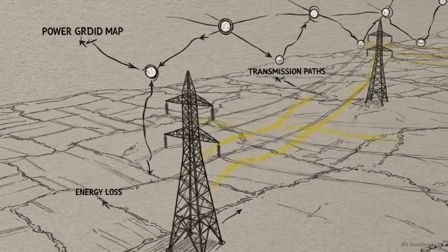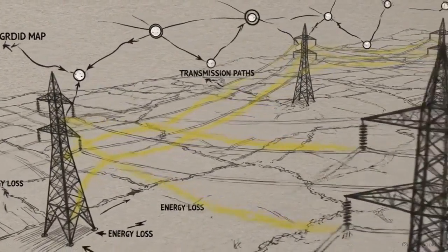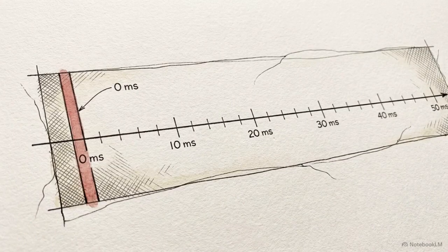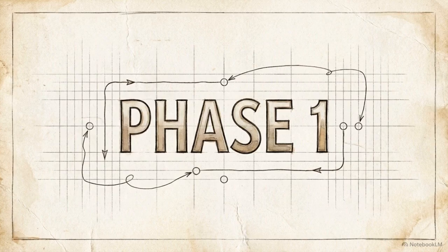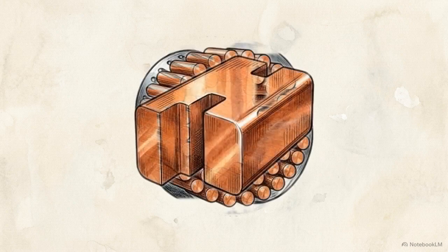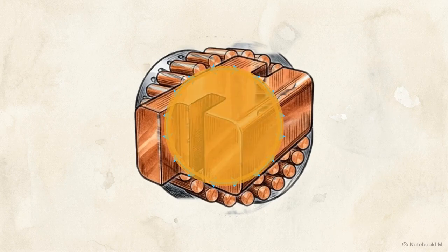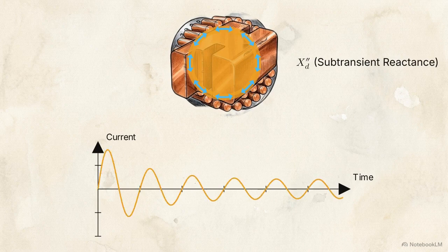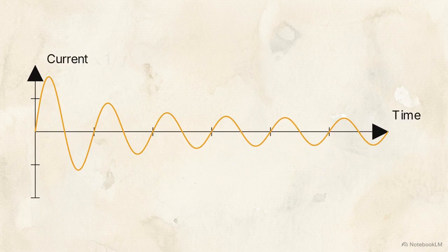These internal machine phases serve as a timeline, directly controlling the scale of the physical threats unleashed on the wider grid. The timeline begins at zero, marking the initiation of the subtransient period, which lasts for roughly 20 milliseconds. Under Lenz's law, the rotor's outer damper windings instantly induce their own currents to oppose the sudden change in stator flux. These currents block the flux at the very edge of the rotor. Because the flux is constrained to the outermost leakage paths, this initial state presents the lowest effective magnetic opposition, known as the subtransient reactance, or X''D.